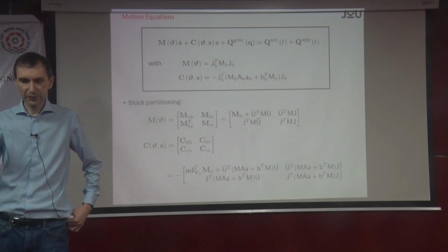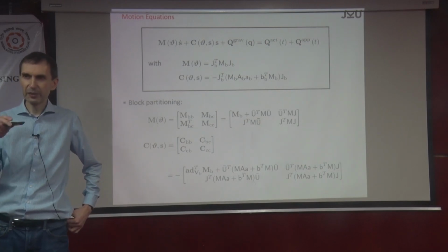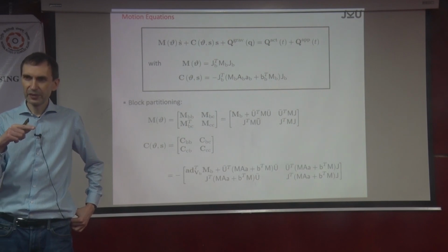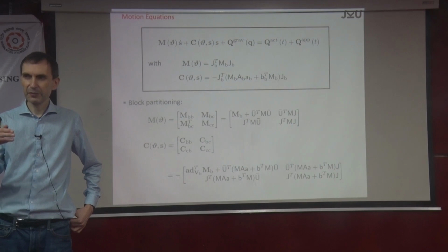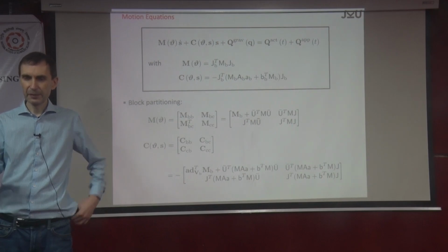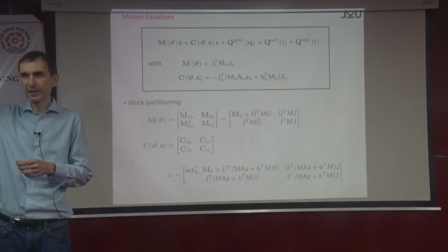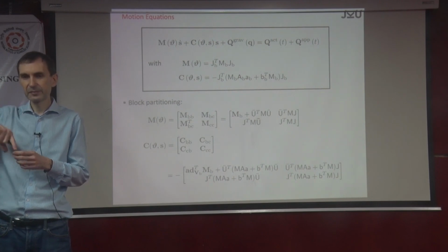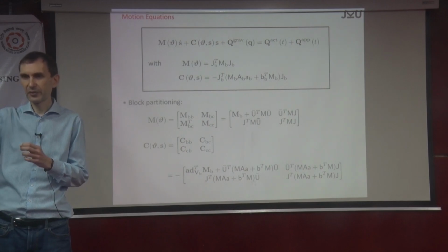You have certain sweeps, like on the motor torque. You give it a certain kind of excitation with a certain frequency. Then you measure the end effector, and you have like a linear transmission channel.